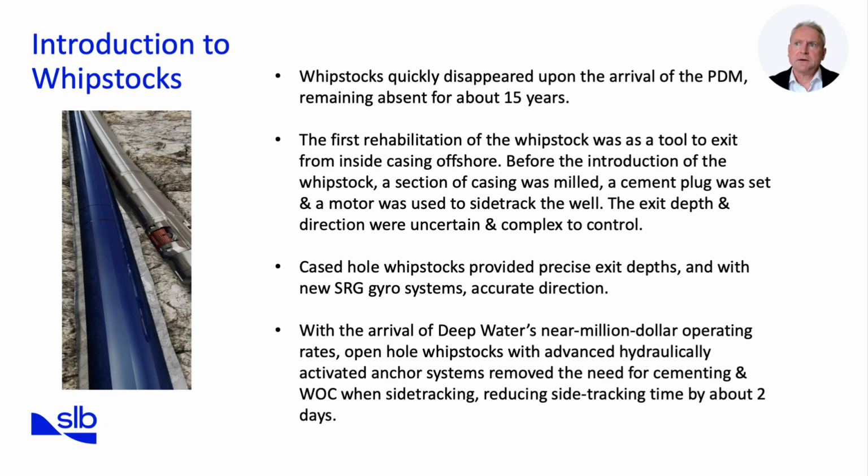Today, they are primarily used offshore for controlled casing exits and sidetracks, proving that an older technology can still have significant value when applied in the right context. Before we move on to the next slide, I have a question. How do we orient the whipstock inside the casing so that the whip face is pointing in the right direction? I will give you a moment to think about this.